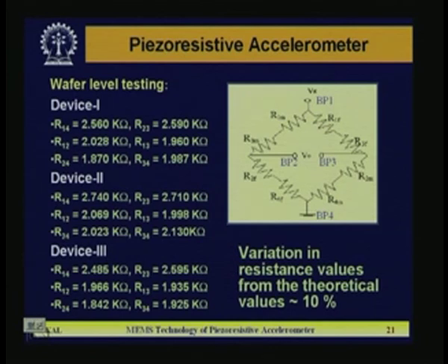That has been measured on bare chip, and 3 devices have been made, and you can see it for different arms. So 1 to 4: 1 means this point is 1, this is the 4th bond point, 2nd bond point and 3rd bond point. If you measure from 1 to 4, the resistance value is 2.56, and from 2 to 3 it is 2.569. So this should be equal. Although in the second decimal place, a little variation is there.